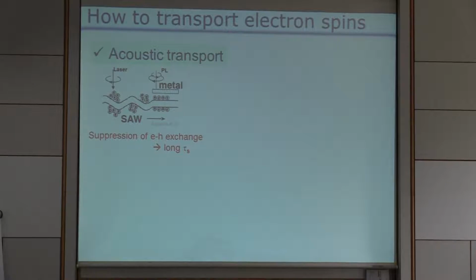And this is another way of spin transport, using the surface acoustic wave. This is the first experiment we have done in NTT. We use the gallium arsenide quantum well structure and apply an acoustic wave, and we observe the electron spins can be transported by the acoustic wave. In this experiment, the suppression of electron-hole exchange interaction is very important to extend the spin lifetime